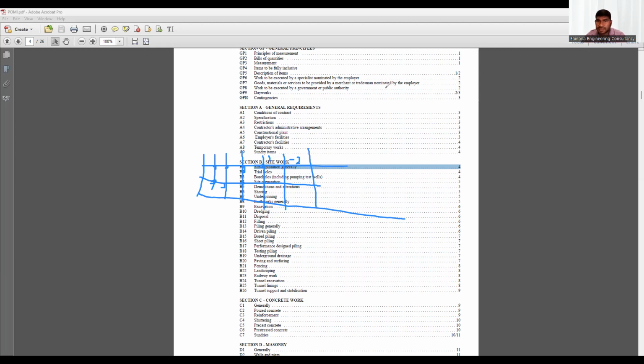And the third one is a kind of ground investigation, or like a scanning of the ground. They call it geophysical, or geotechnical, I think, which gives some information on the underground existing services or underground existing objects. If there is an object like a concrete block or existing cables or existing pipes or whatever it is in the underground, it will show in the graph that there is some object below 2 meters of the ground, something like that. So that is an underground survey.